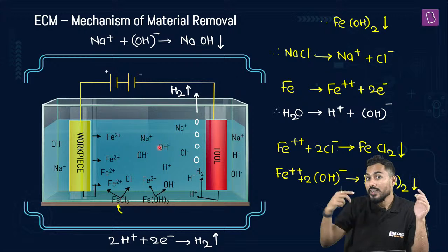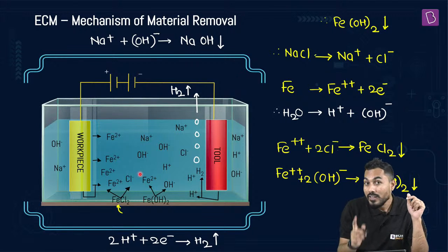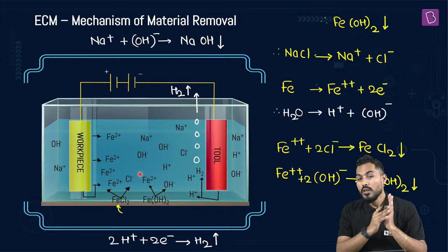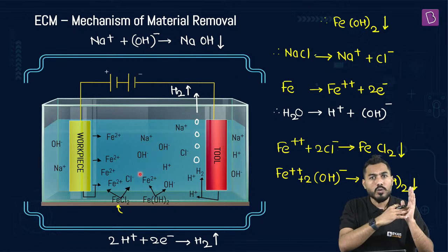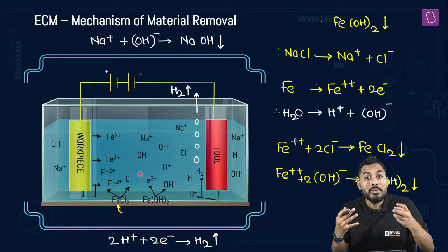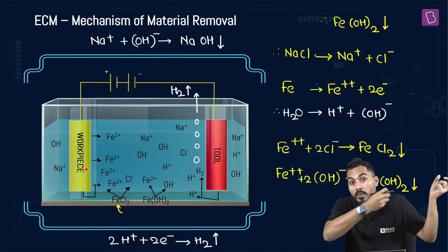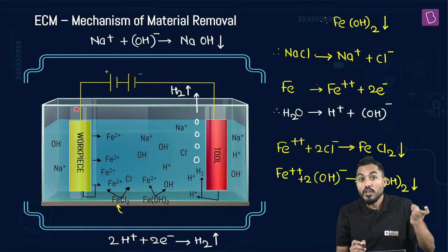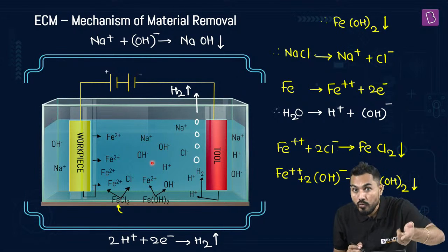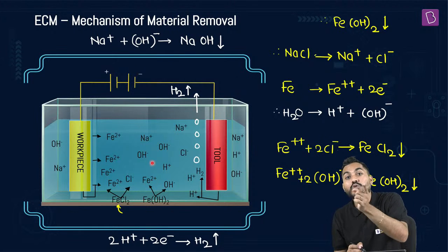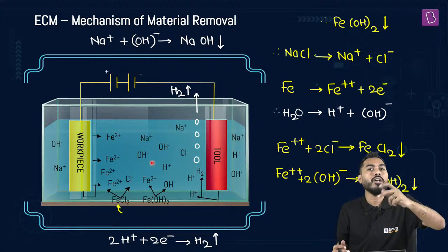As the time required is less, and there is extremely high conductivity of the solution, can I say that the energy required for traveling through that conducting solution will be less. So more energy will be utilized to generate electromotive force, and because of that force, more and more ions will get depleted from the workpiece. So naturally, the number of ions depleted because of more electromotive force leads to more material removal. Natural statement, and therefore I'll say that material removal rate will be higher.